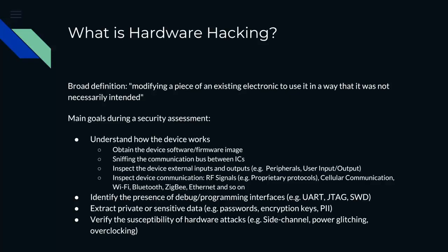Also identify the presence of debug programming interfaces on the PCB itself, on the device itself, like UART, JTAG, SWD. Try to extract private or sensitive data from the device. For instance, passwords, encryption keys, and personally identifiable information. And verify the susceptibility to hardware attacks, for instance, side-channel attacks, power glitching, and overclocking.